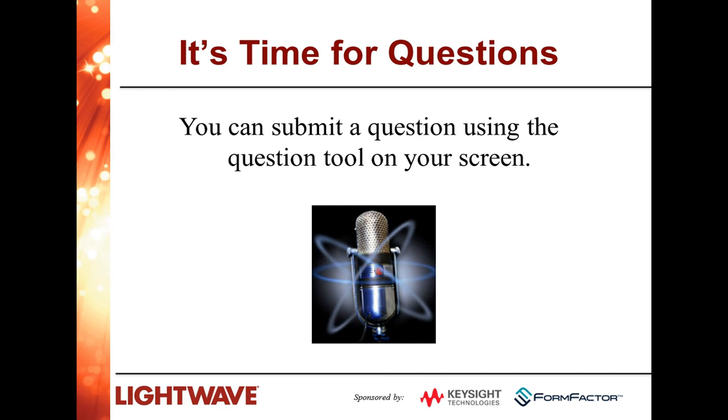Oh, sure. That one, we have 2 needs here. We have 2 functions. One function is the alignment function, and the other is the measurement function. For the alignment function, we need to capture a fairly large dynamic range from, depending on your source setting, your insertion loss, how much light makes it through when you're not coupled or you're slightly off axis and only a little bit is getting through. So we have a log compressed optical power meter that feeds the alignment system. So the voltage applied at the alignment controller is proportional to the log of the power arriving at the optical meter.